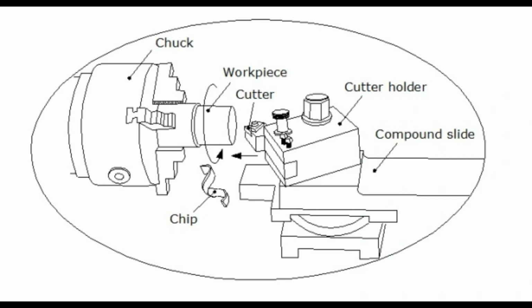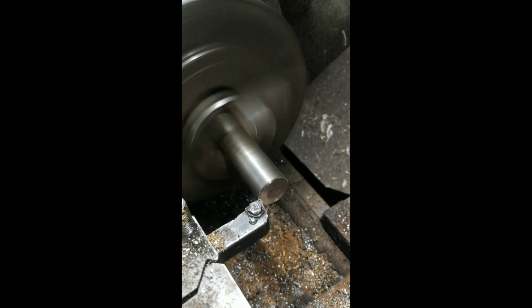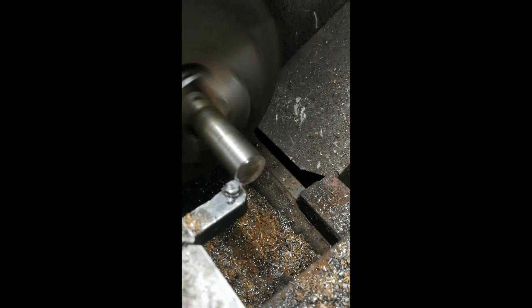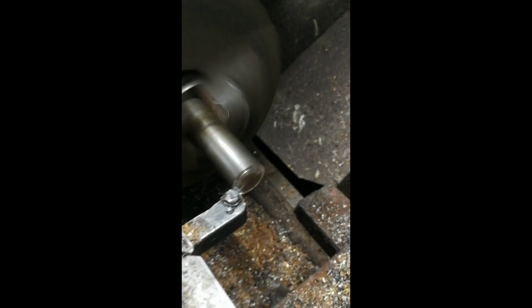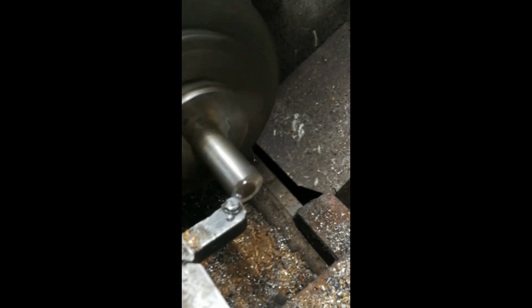This is to allow finely controlled adjustments to be made for facing and also for getting the tool safely to the edge of the work, but with practice, the latter too can be learnt with skill on the main saddle handle, even more so when used in conjunction with a digital readout.